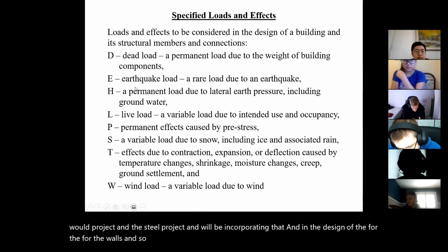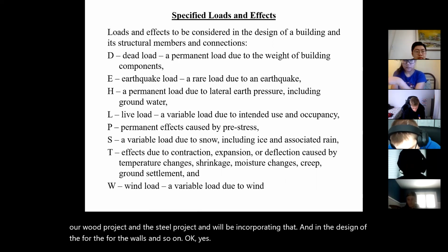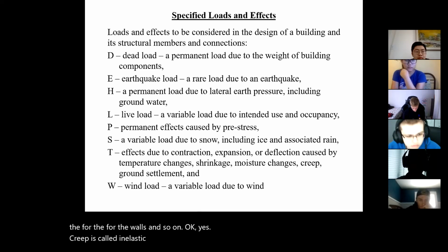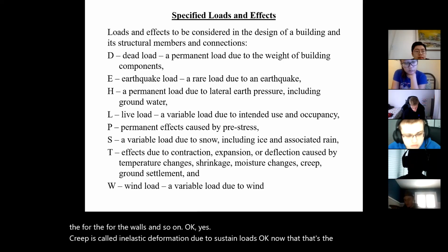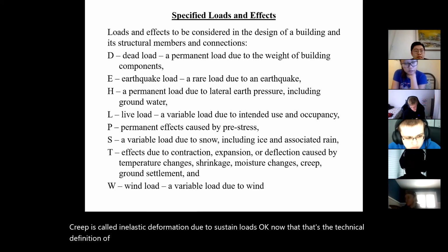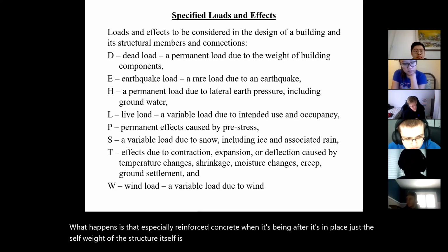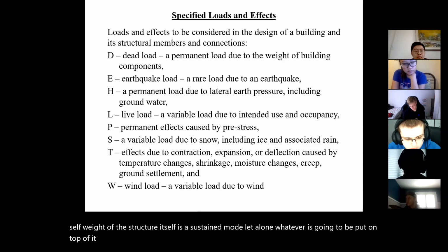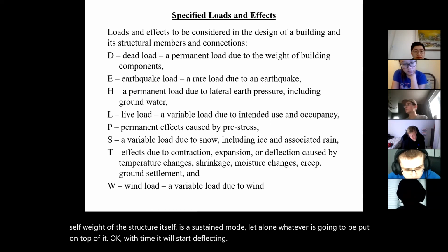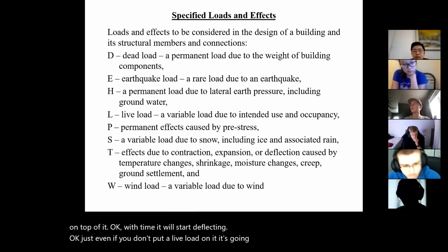Okay. Sir? Yes. Can you go over what creep is again? Creep is called inelastic deformation due to sustained loads. Okay. Now that's the technical definition of creep. What happens is that, especially in reinforced concrete, after it's in place, just the self-weight of the structure itself is a sustained load, let alone whatever is going to be put on top of it. Okay. With time, it will start deflecting. Even if you don't put a live load on it, it's going to deflect under its own weight.